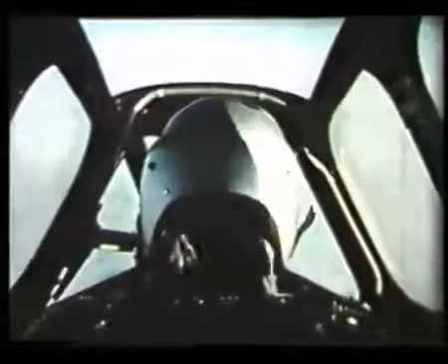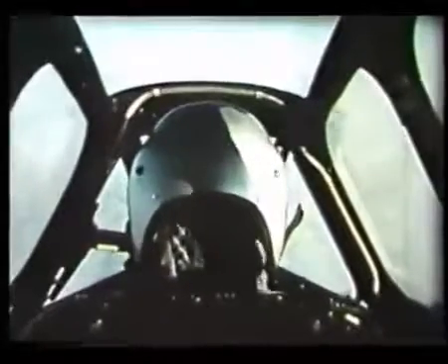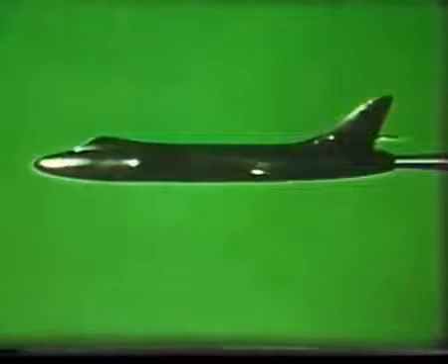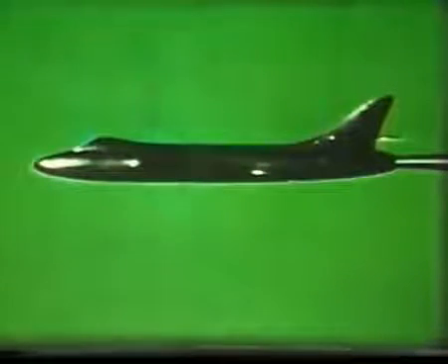These are the chief troubles which the pilot may meet when he comes up against the shock stall. But shock waves don't only appear on wings. Speed up of the airflow occurs around the canopy and many other parts of an aircraft. Wherever it's great enough, there shock waves will form. Shock waves cause a vast increase in drag and may cause serious control troubles.